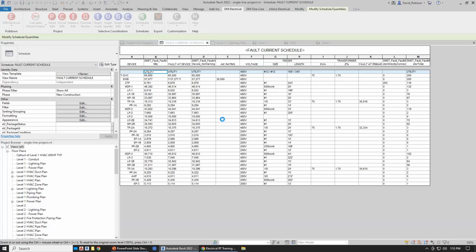So the first part of getting the fault right for your automatic transfer switches is that you have to model it properly in Revit. If you don't know how to do that, we actually have a knowledge base article on how to do that, because setting up a transfer switch is a little bit tricky in Revit. So you get the transfer switch in there, you get it connected to two different pieces. Then you can see we have two basically source devices here, because that LP2 is not connected to anything. So it could act as a generator or whatever that's going to be. And since it's on the secondary of the ATS, it's not showing the things below it. So it's just sitting here by itself.